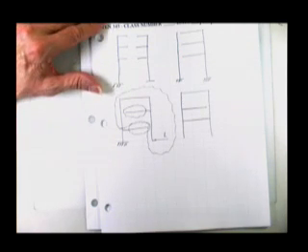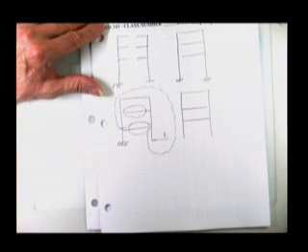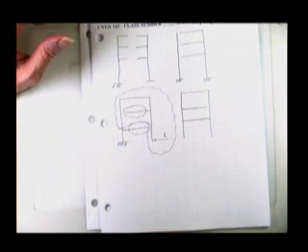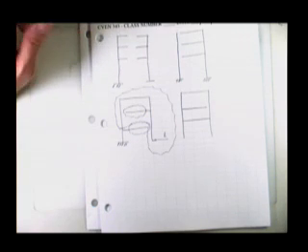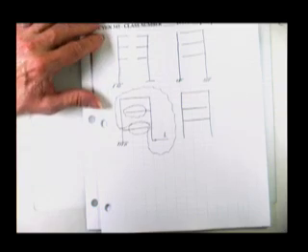Does that work with this man? I'm sorry? It will just float. Yeah, isn't it just kind of floating? Yeah, I'd say that any load on that would probably kill somebody. That's not a good primary structure. You say, well, we released 9 redundants. You did indeed, but you didn't have a stable structure when you finished, and therefore that would not work.